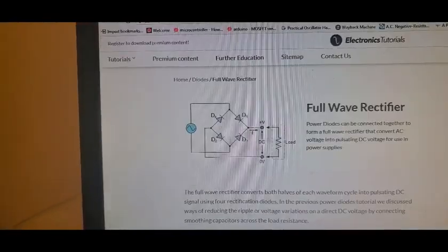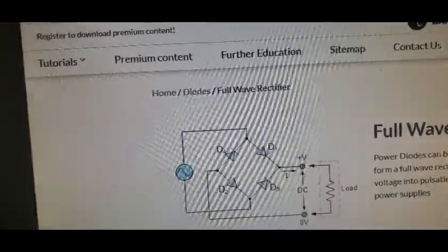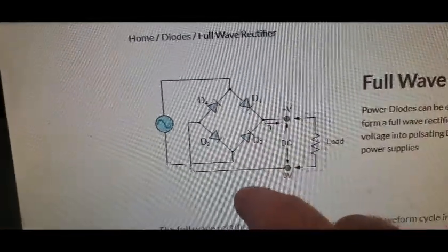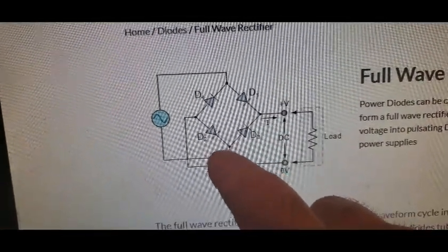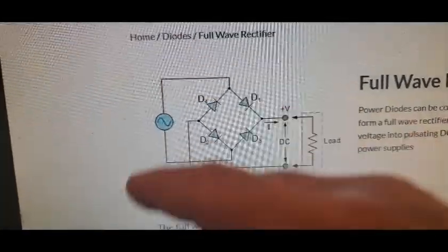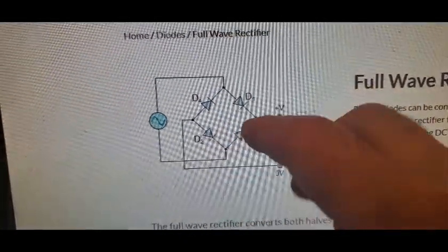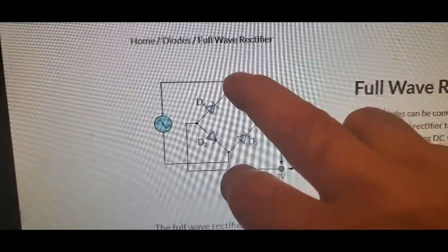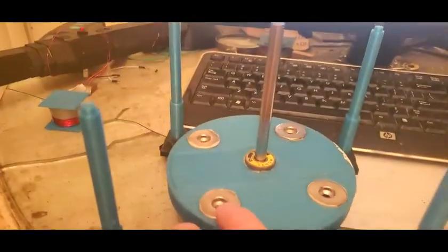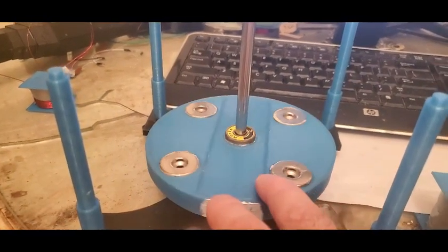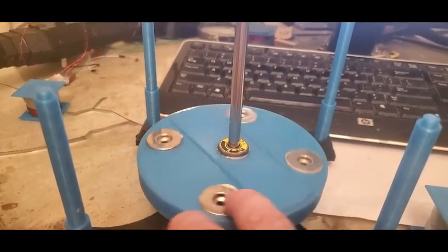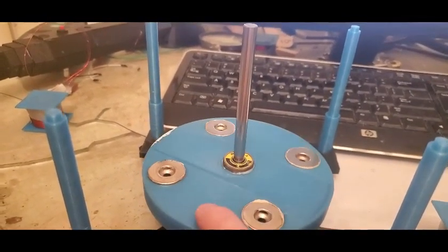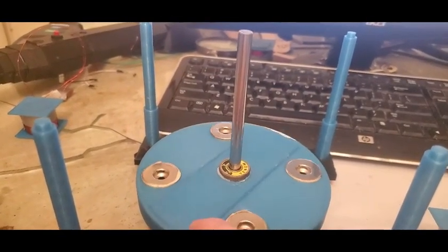So now you go back to that clever setup, I don't know who invented it. Maybe someone will teach me. The clever setup here of the 4 diodes, where now you can have it boom, boom, boom, boom, and it's always, these two are always isolated by diodes. So when you go to a bipolar machine, you want to use a full wave bridge rectifier. When you go to a monopole, you can use either.